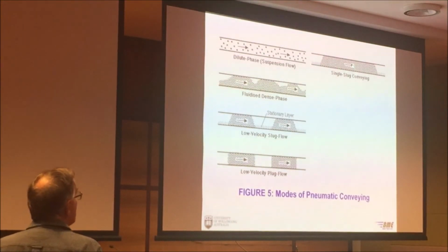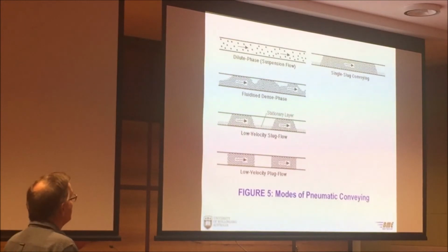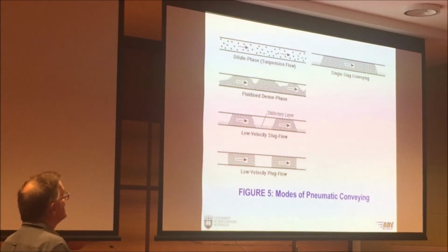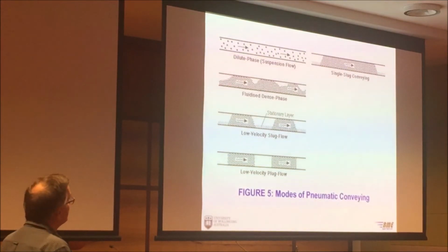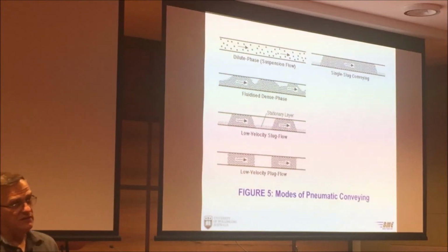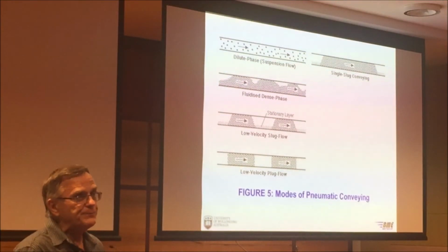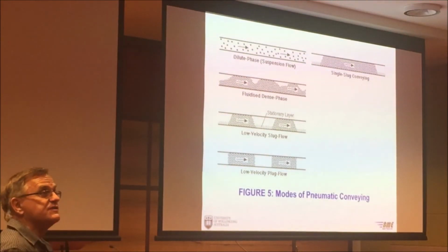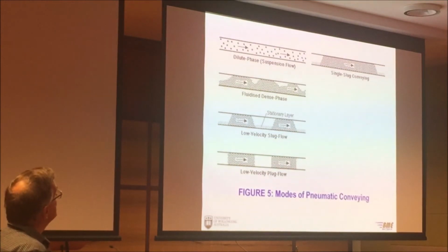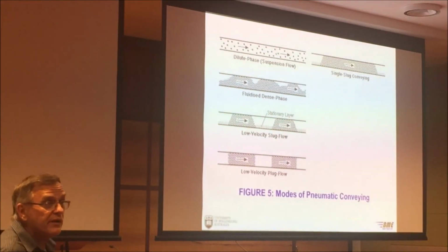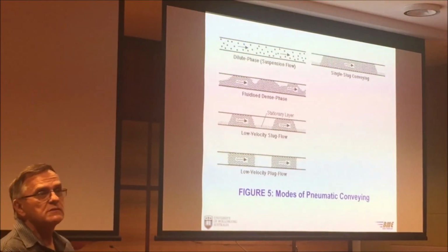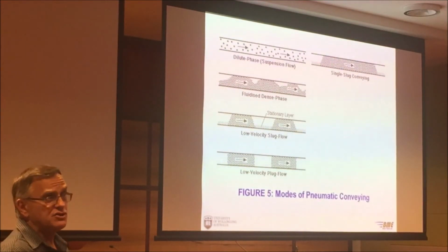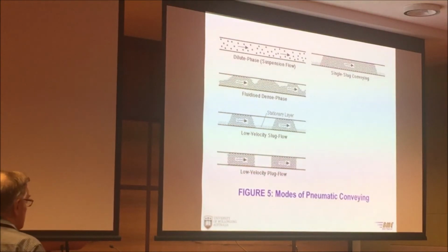So those materials, the only other form of pneumatic conveying is dilute phase, because these materials suited here can't be done this way. So if you start conveying rocks in dilute phase, you need very high velocity, and it doesn't become practical. So you can, for short distances, 100 metres, 200 metres, and for low tonnages, 10 tonnes per hour, something like that, you can convey these nasty materials quite well. Crushed coal, crushed rocks.